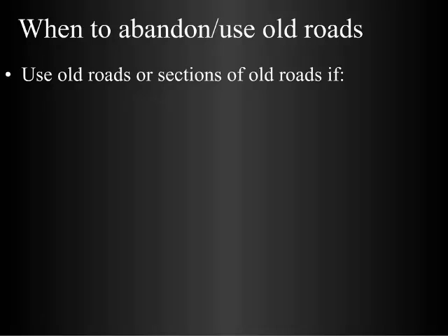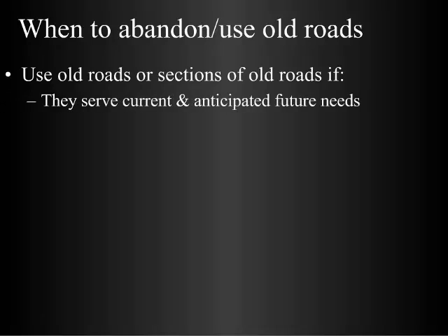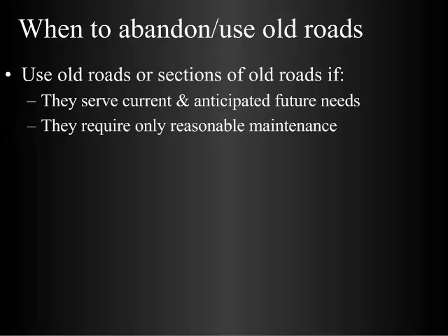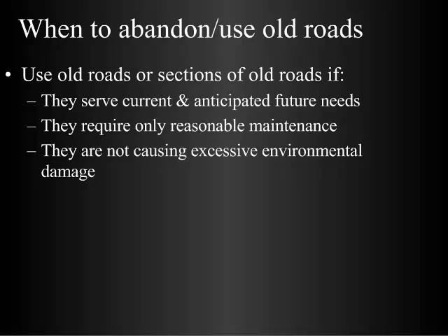The other thing is, okay, when do you want to use the old road? It's basically the converse of what was talked about before. If an old road's out there and it meets your current needs and you think it's going to meet your future needs, then it's good to use, if the maintenance is reasonable and not causing excessive environmental damage.